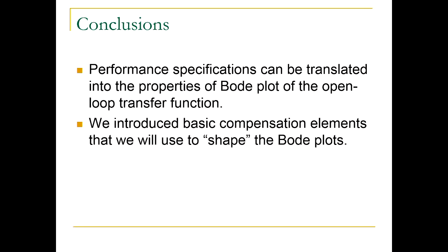Okay, so I'm realizing it's a short lecture, but we will have another one this afternoon, so it's probably okay. So what we saw today is different Bode diagrams which you need to really learn how to use. So there are different parameters in these transfer functions that you can tune. These parameters would affect phase and gain plots of compensator Bode diagrams. And these are actually, like I call them, Legos. I give you the plant Bode plot, I give you the performance specifications. You need to come up with these Legos. You need to design Legos so that when you add them to the plant plots, you satisfy all specifications. So that's what loop shaping is all about, right?